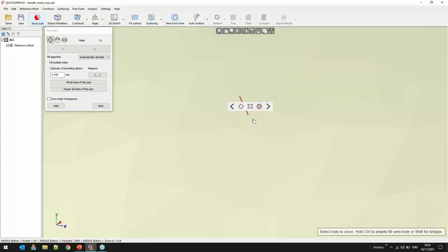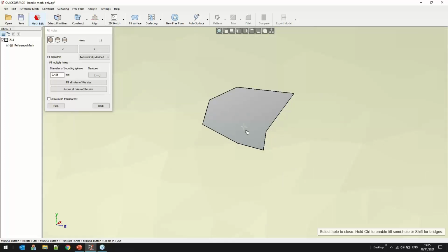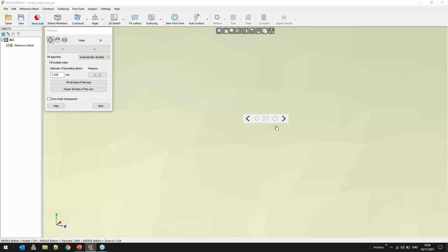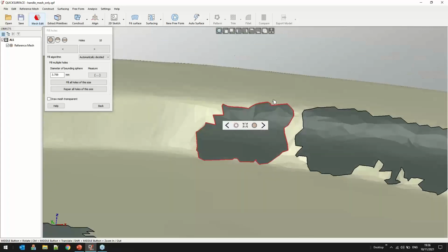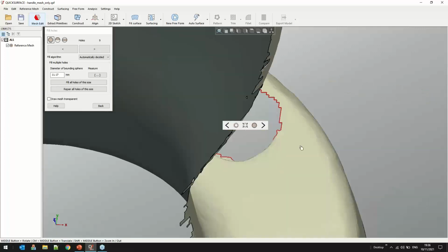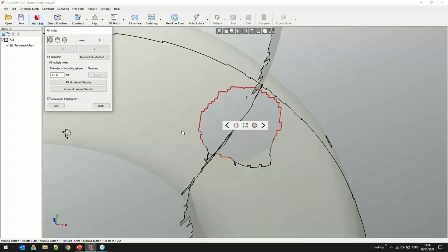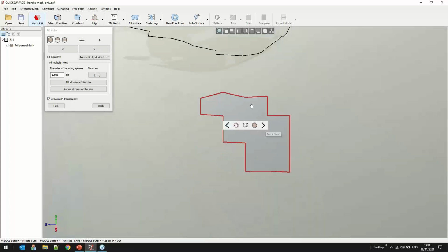You can just click and try to fill it. The problem is that sometimes the hole is identified like this one. So we have a feature here called expand the selected hole. If something is really badly oriented, you can help the algorithm to enlarge this hole. And when you're happy with this, you can just fill it. In the same way as with the individual meshes, you can safely track and go through all the holes. As you can see now, I don't really see the hole, so you can always render the mesh transparent. This is actually not a nice hole to be filled right now.